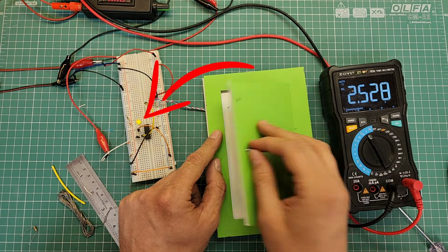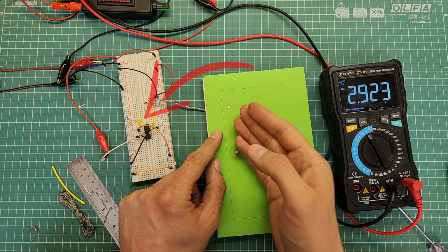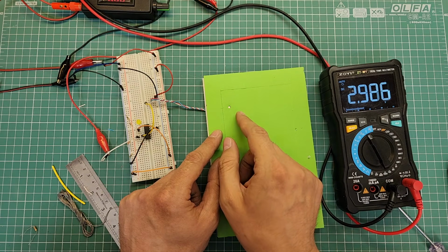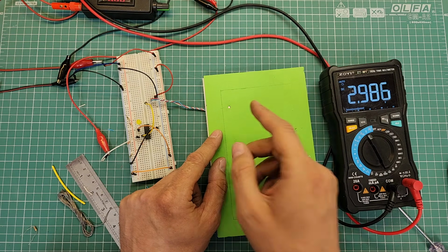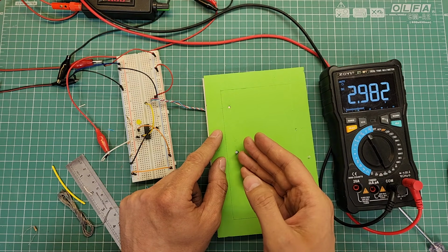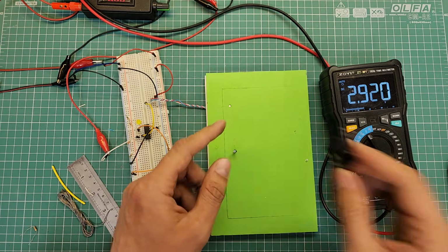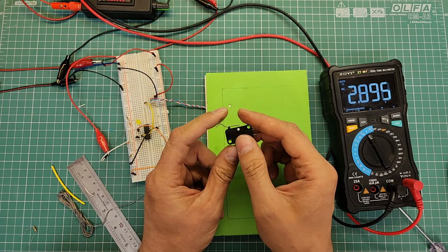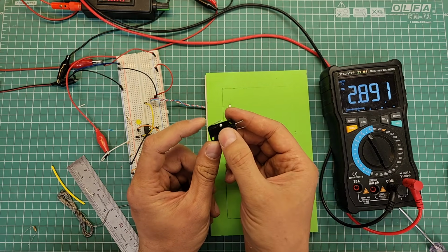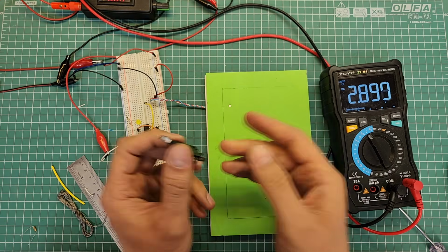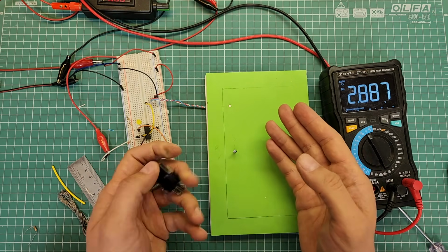This sensor is used in most refrigerators to detect if the door is open. See, when the door is closed, the magnet is near the sensor and the op-amp turns off the LED. In old refrigerators, mechanical switches were used to turn on a bulb inside the refrigerator, something like these limit switches. But these magnet sensors are hidden, making them cleaner than those switches.